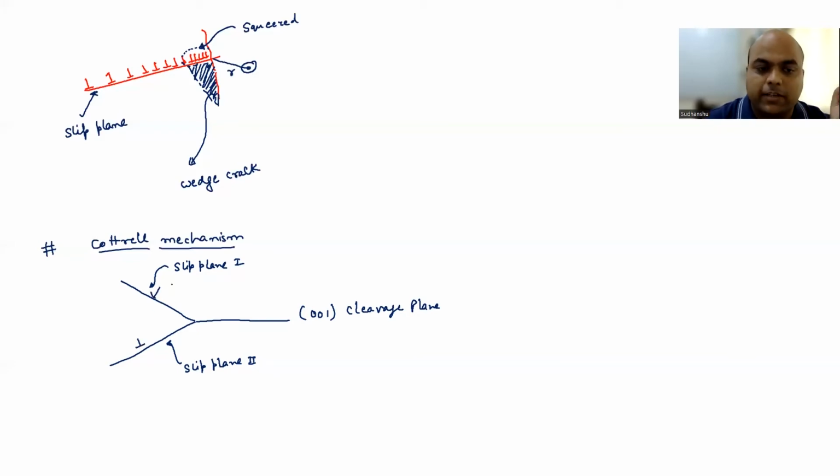Okay, now these dislocations are moving in this slip plane as well as this slip plane, but now they are interacting here. Now they cannot move, so you are going to generate a crack. Because again, you can think of this squeezing phenomenon, or because of the pileup, you have a very high amount of stress, which can lead to the generation of a crack. So this is like the Lomer-Cottrell barrier, another mechanism.